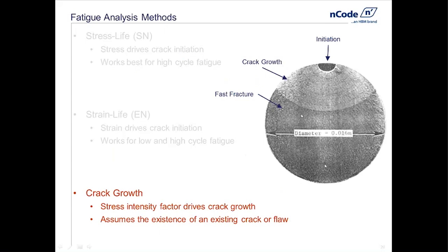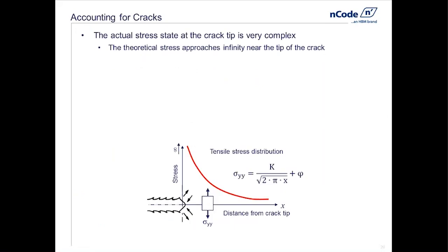So to understand cracks, what we have to do is think a little bit differently. We've been looking at stresses and strains on, by default, the uncracked continuous media. So linear elastic stress strain theory. Now we have a crack, and a crack is the worst kind of stress concentration ever because it's really, really severe. As a matter of fact, a crack, by definition, is an infinitely sharp, 0 radius on the end here. Radius goes to 0, which means then that theoretically the stresses should become infinite there.